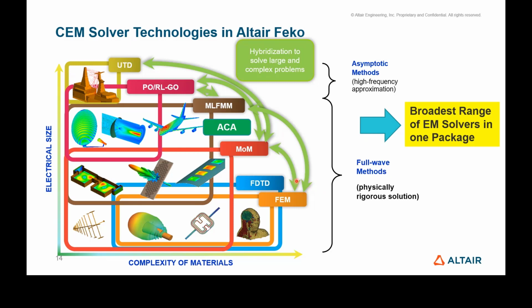But of course, we also hybridize them. That means FEM works with method of moments as a bounding boundary, and also with MLFMM. So you don't have to have a big airbox around your object. You can actually have it very conformal to your object. But of course, we also support the airbox with FEM. Same thing with FDTD, because method of moments hybridizes with physical optics, as well as UTD, and MLFMM hybridizes with physical optics as well. So this is actually a unique combination in Feko, which gives you the coupling between various methods because they're hybridized with each other.